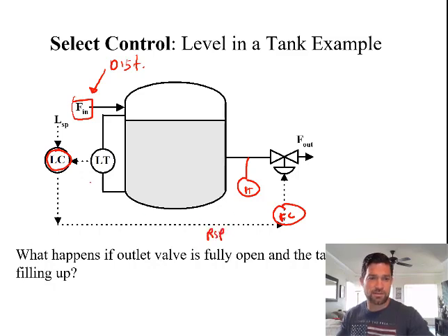Our primary control objective is the control in the level. So the level controller sends a remote set point to the flow controller. It takes the measurement of the flow and we open or close this valve as needed. Okay, so now we have this cascaded. What this cascade system is going to do is account for changes in pressure downstream from this valve to keep this at the target flow.